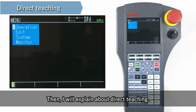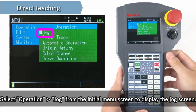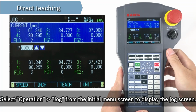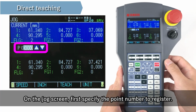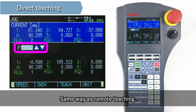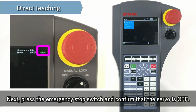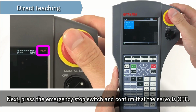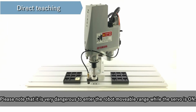Then, I will explain about direct teaching. Select Operation then Jog from the initial menu screen to display the jog screen. On the jog screen, first specify the point number to register, same way as remote teaching. Next, press the emergency stop switch and confirm that the servo is off. Please note that it is very dangerous to enter the robot movable range while the servo is on.